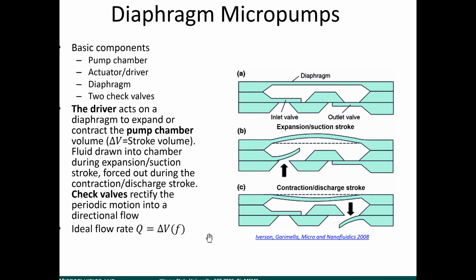It was made up of a diaphragm, and that diaphragm was actually an electrode. So when you put a positive charge on this electrode and a negative charge on the valve seat below it, the membrane would deflect. Kind of like the micromirrors that we talked about at the beginning. You put a voltage across 2 plates and they get attracted to one another.